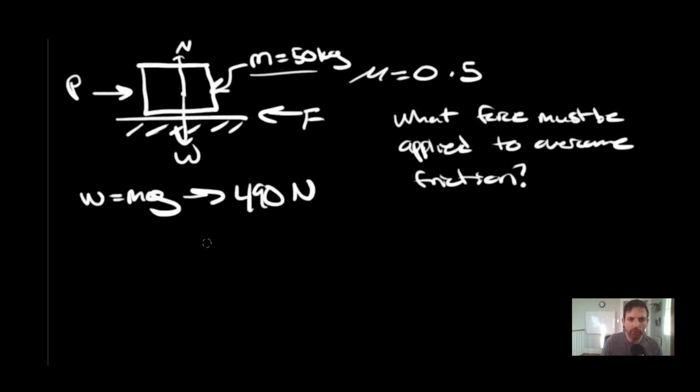All right. So here's what we know. We have some force P, and what we have to realize is, P from the previous example, the force static, is going to be the same in this example, because whenever I reach this maximum static friction force, that means it's going to break loose from the surface to allow the object to actually be pushed, right?